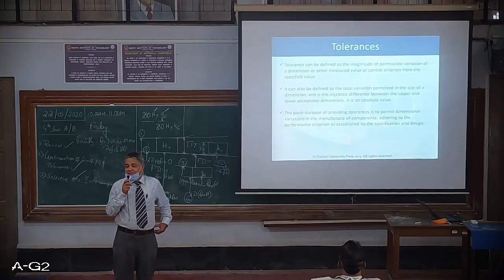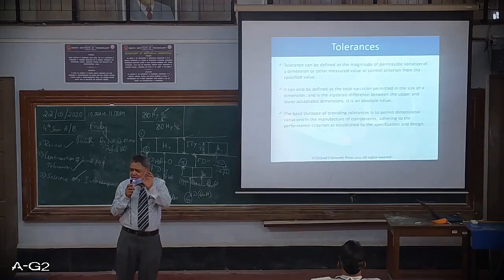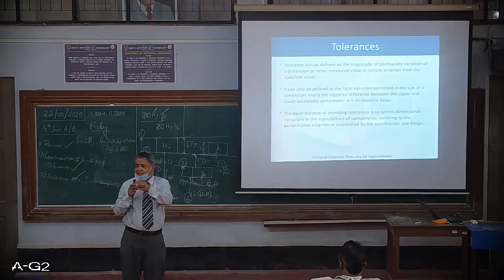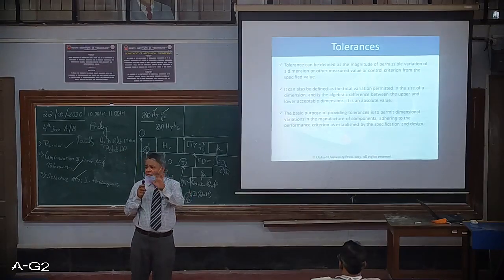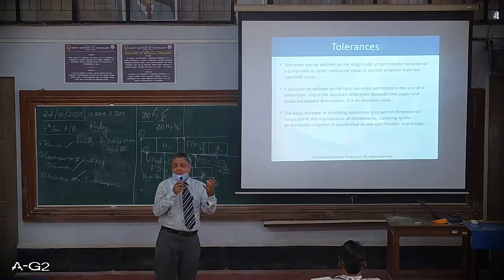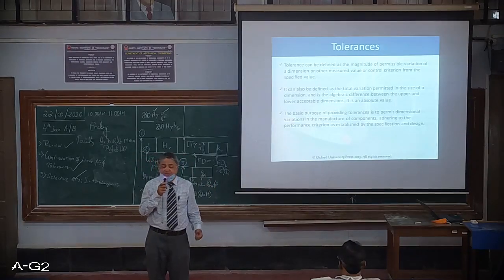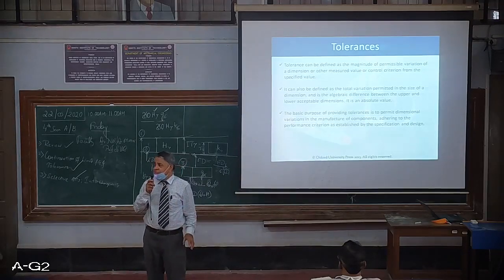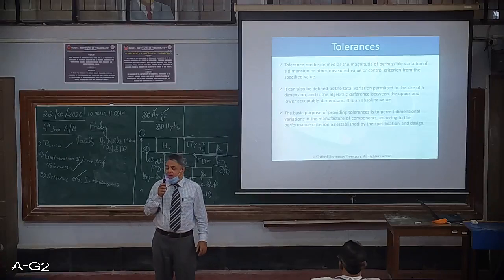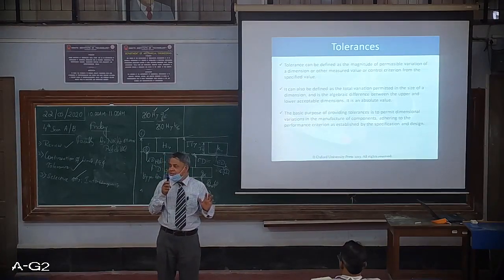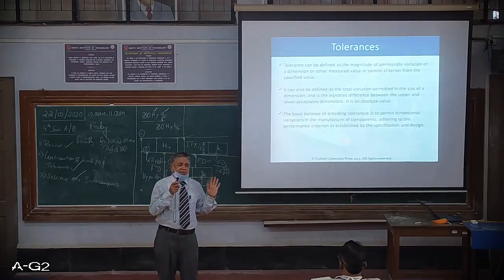Thank you, Nikhil. You have corrected it, saying that selective assembly gives the correct or consistent fit, and that it is mostly used in aerospace and automobile industries. Now I can take the example of a cylinder and piston mechanism of an IC engine. It may be working with plus or minus 2 microns tolerances. In that case, manufacturing the cylinder or piston within 2 microns is not possible. It will result in larger rejects.